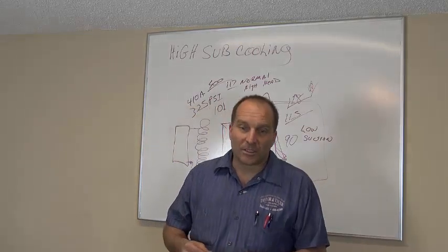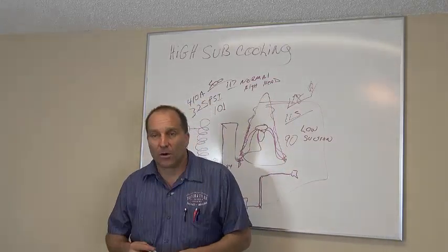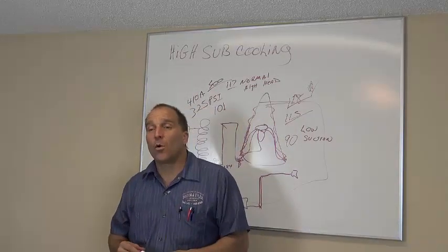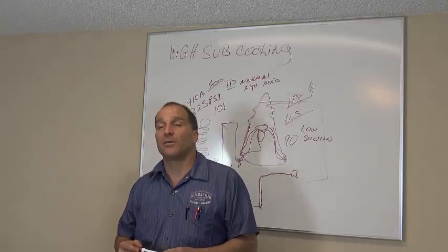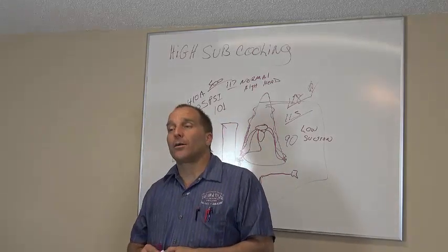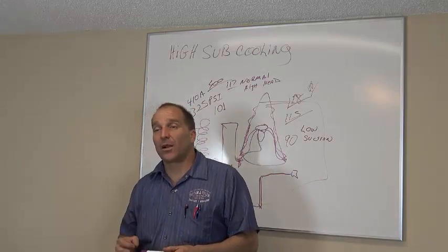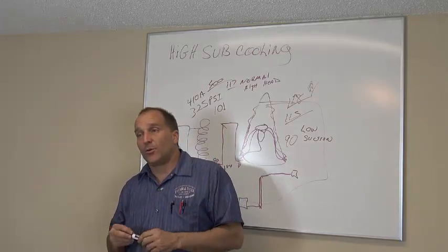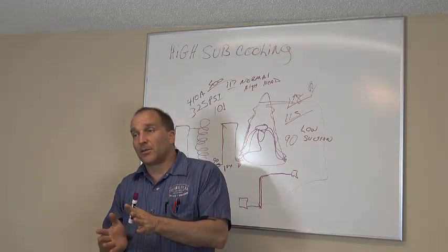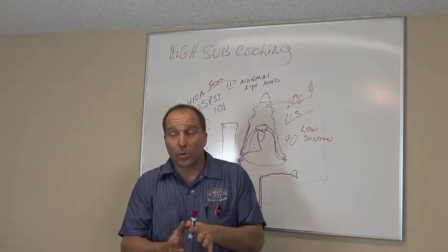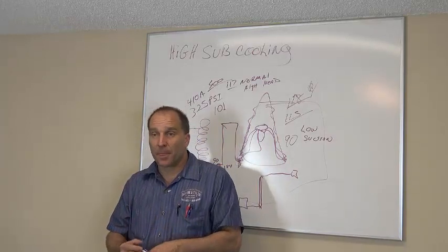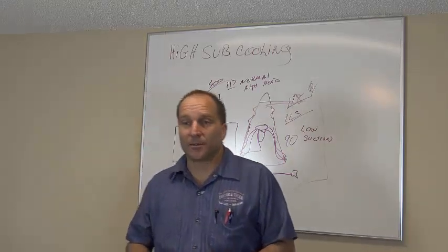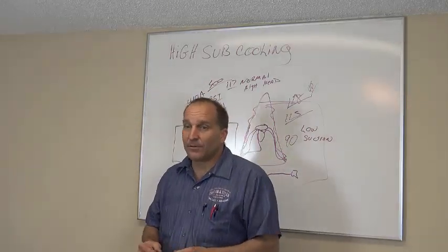Now, the Ruud system, the UA17 model, and if you put in an RCF 6021 SEAM CA coil, that is an electronic expansion valve on that evaporator coil. So you wire this evaporator coil in because it's an electronic TXV, and the electronic TXV wires into Y1 and Y2. That Y1 and Y2 electronically opens that expansion valve up because of the first stage in cooling and the second stage in cooling. Okay? Whereas your typical expansion valve does not have any voltage going to it, this one does. Okay? Uses DC voltage going to it. Okay?